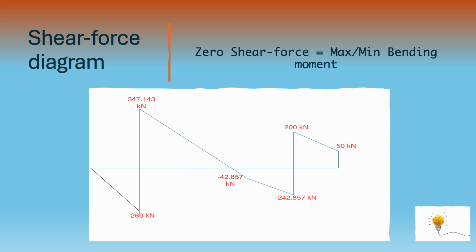Shear force diagram, what do we have? We've got first triangle, which is on the negative side from the 80 kilonewton per meter and the 50 kilonewton per meter. We've got our first triangle, then we've got our next right angle triangle for bending moment, and we've got this small one over here, small triangle at that point. Okay, that's another triangle on the negative side. Then we've got a trapezoid. This is on the positive side, and those are our points.